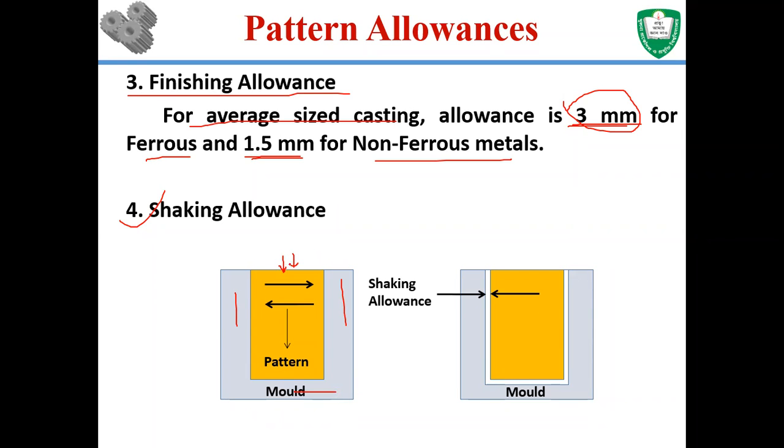And also, you need to provide a screw here, and you need to have that provision in the pattern so that you can fix the screw in here, and then you apply force in this way and that way to get the other two sides released from the packing of the sand. And if you do that, there might be an increase of dimension, right? The cavity dimension will increase.